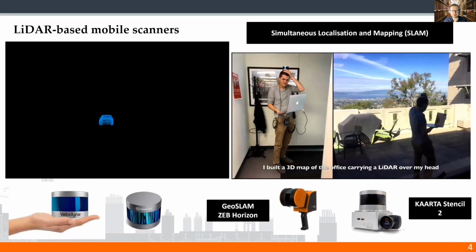Now, let's dive slightly deeper into how mobile lidar-based scanners work. I will skip how static scanners operate because they are way more known to the construction industry and they do not need much explanation. So let's see what a lidar is and how it works. A lidar is such a pack manufactured currently by many companies such as Velodyne and RoboSense, which gained popularity in the last 5 years, mainly due to the increasing interest in autonomous driving.